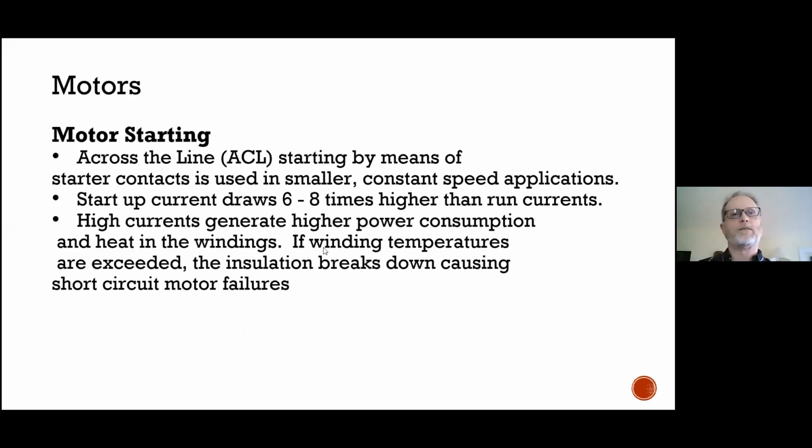So across the line start means basically using the direct connections, but mostly for, again, as it mentions here, much smaller motors, so they don't have such a high draw on the current. Because, as the slide mentions, the inrush, or the actual draw of current when a motor is called for, and again, you think about a remote operated system, a switch or a level recorder or a float switch turns on, tells the motor to turn on because the reservoir is low and needs to be refilled.